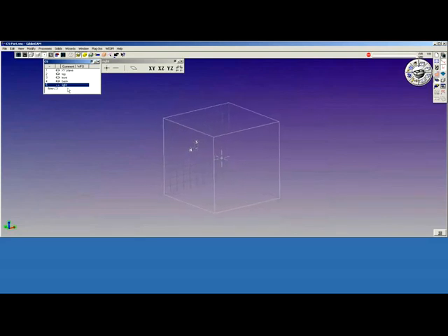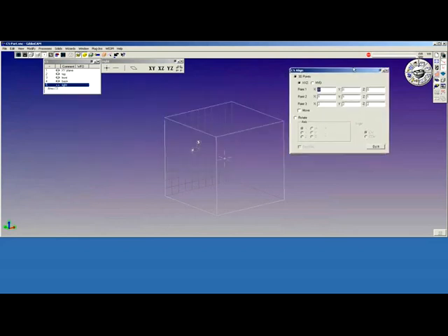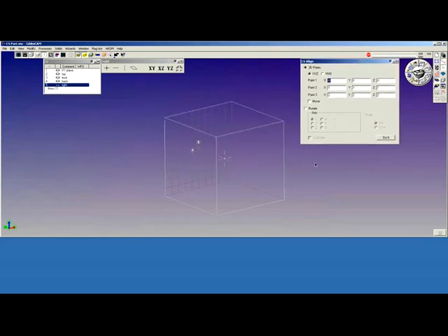You understand that by building this new CS, we've duplicated the existing CS in its exact location. And now I'll activate my align CS plane tile, bring up the dialog, and see what I have available to me. The default selection is a coordinate system aligned through 3 points in space.